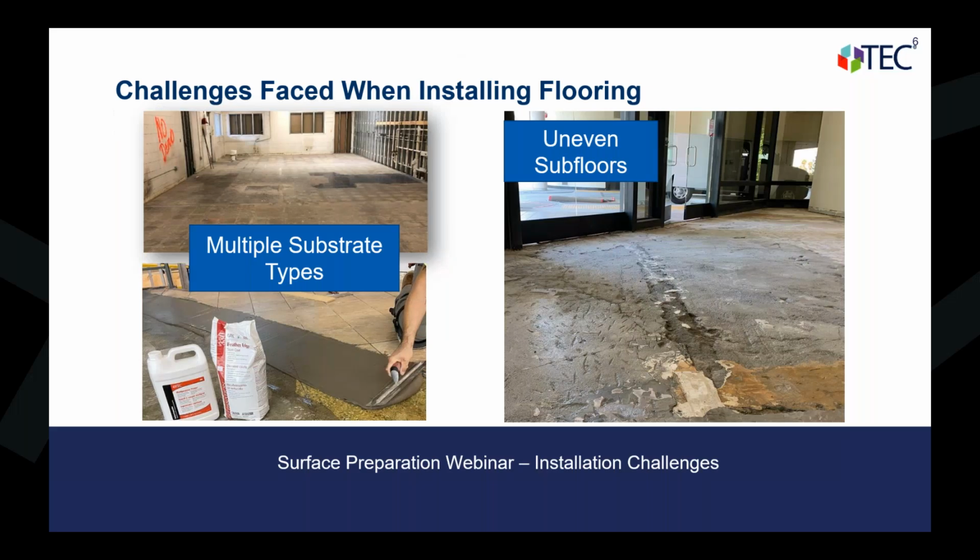Here's some challenges. You can see here that the floor is not flat enough. It has some debris. Any of these debris on the uneven floor side of it here, any of those chunks that are loose, you're going to need to take care of. You need to clean that up, get all the debris out, make sure it's a clean, sound, dry substrate so you can then adhere the material that you're going to need, whether it's a self-leveling underlayment or a patch, to be able to fix that and be able to tile over the top of that.